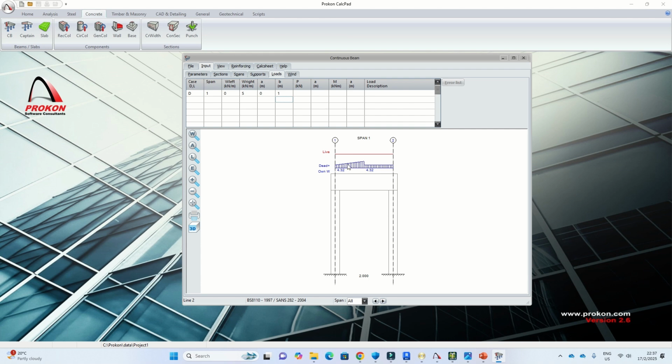As you can see, this load has only been added on one side. Now let's go for the other one. Let's say this was 10 or 15, I think 15. As you can see, this is the pattern of the load, but it's not the end of the story. Now we have another one which is starting at 15 and it's going to end at 0, starting at point number 1 and ending at point number 2. As you can see, I created a triangular load. So this is a method that you can use to get the necessary loading. So you only look at the extra dead load.